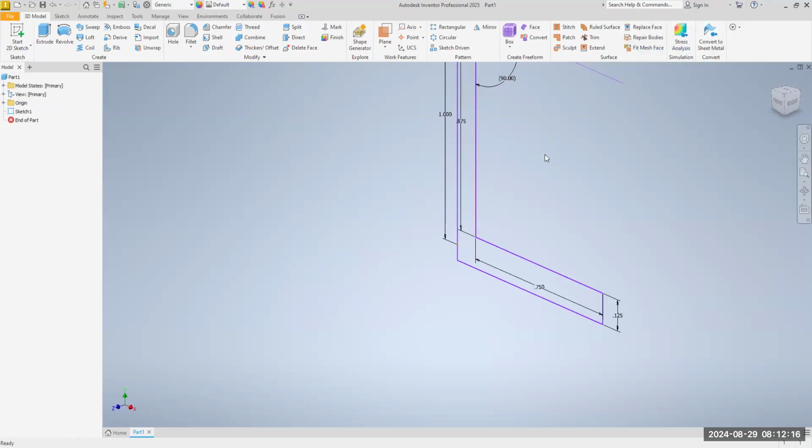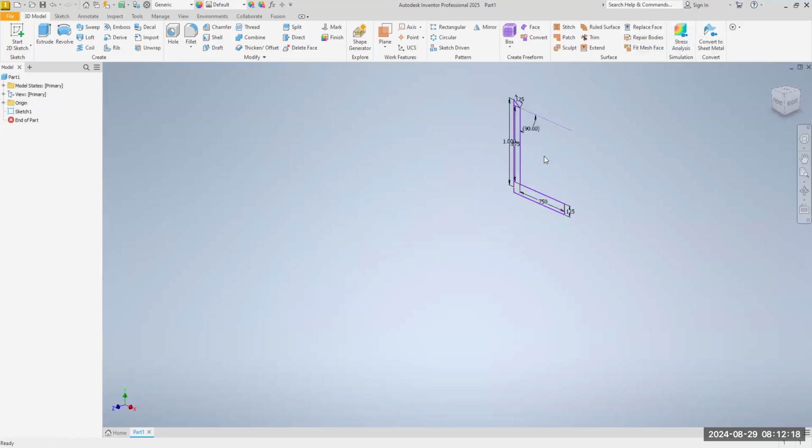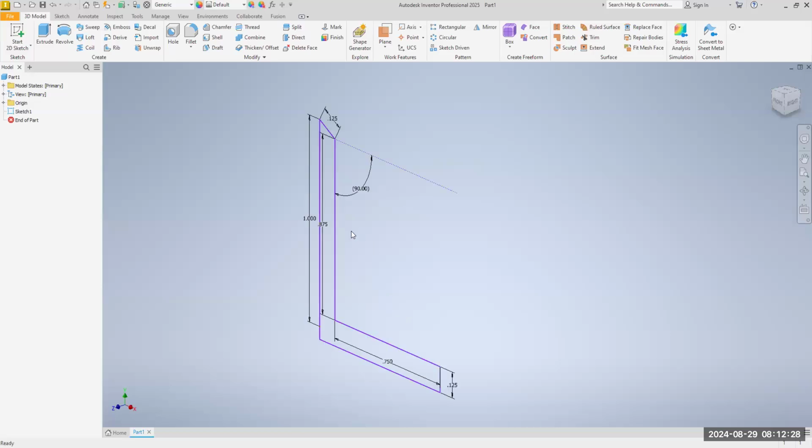What do I do? Well, I can rotate my scroll wheel, hold down the scroll wheel and move the mouse, and then rotate the scroll wheel again to zoom in. This is called extrusions. So look, I'm going to click on extrusion. Watch what happens. Here's the magic.